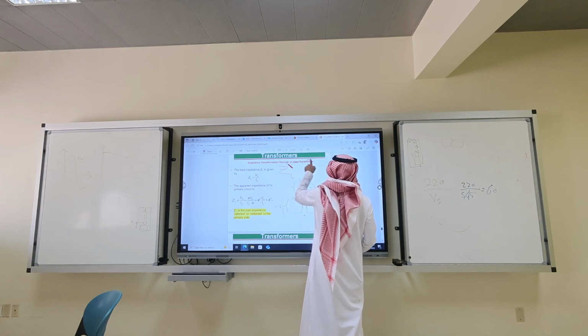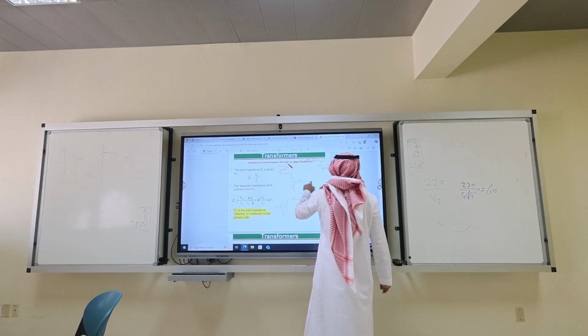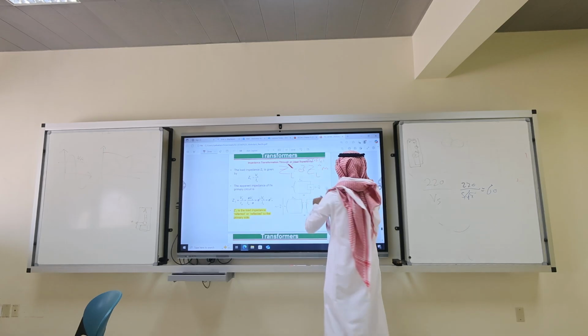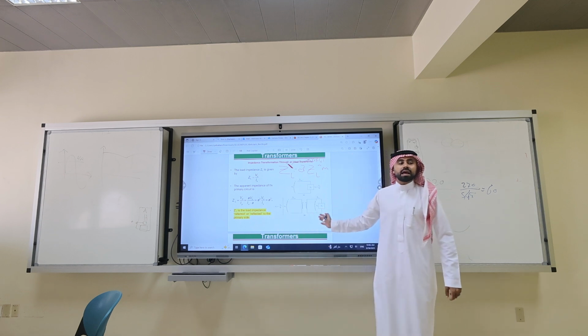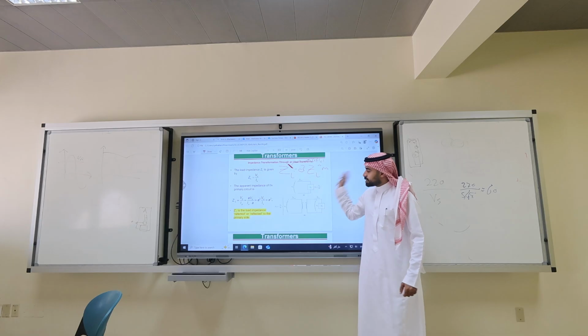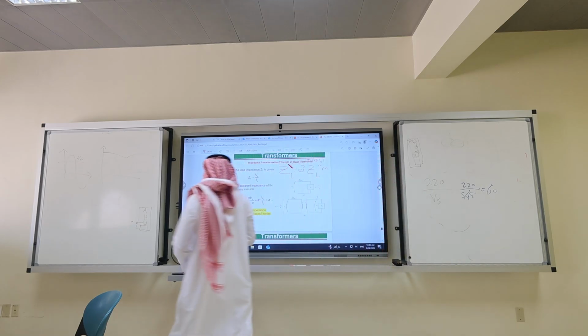What does the bar mean? Reflected on primary. Equal a squared times the original Z L. So you can reflect it and break the electrical isolation. And you can connect it here and get rid of the transformer stage. You did this in the previous course.